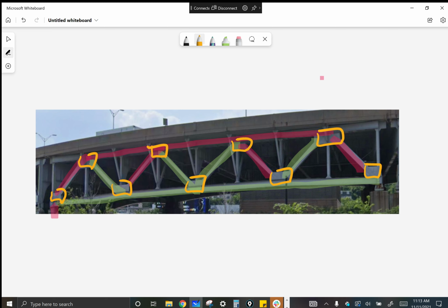But we also have all this other stuff, like this right here. This is another triangle that's perpendicular to the plane, right? All of these are bracing. These here, they are not in the theory at all. Now these are zero force members, the ones coming in, or they could be right here. Those are in the plane. But this other stuff, if you think about it, is outside the plane, so it doesn't exist in the theory. It's part of that box that I drew one time for simple. Maybe I'll do that in a second.